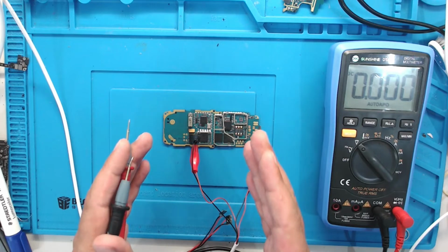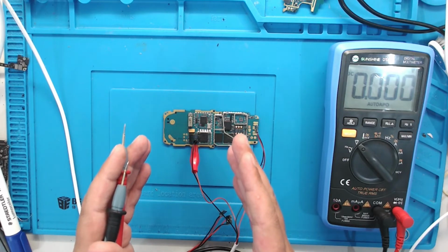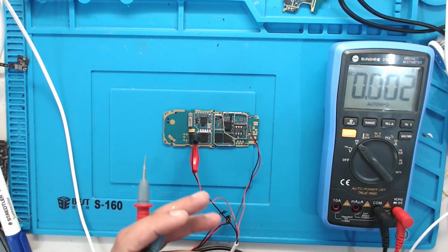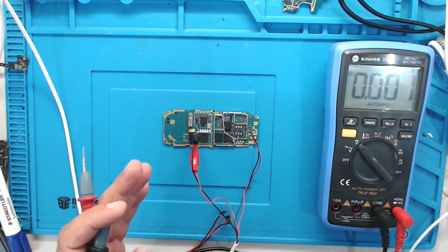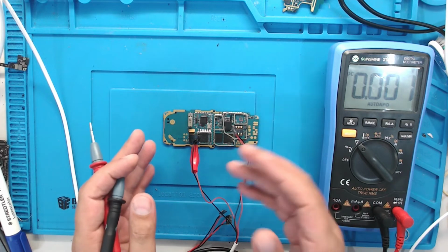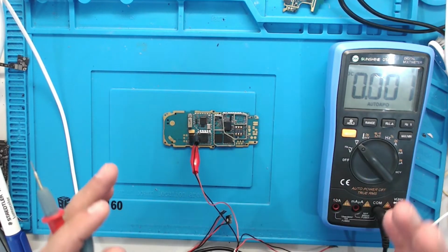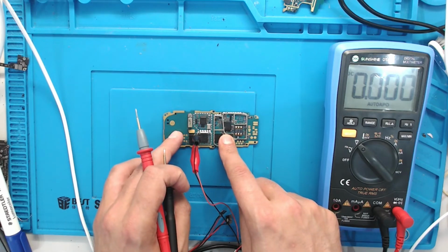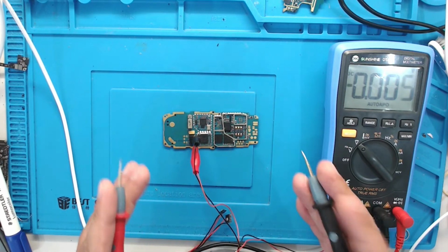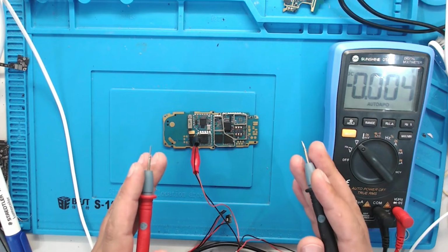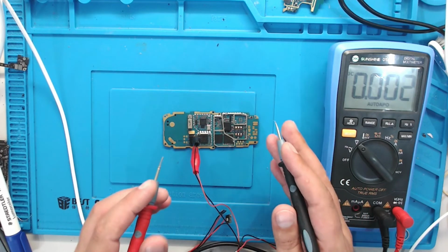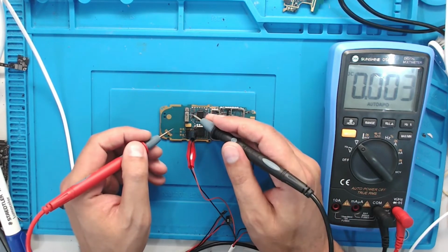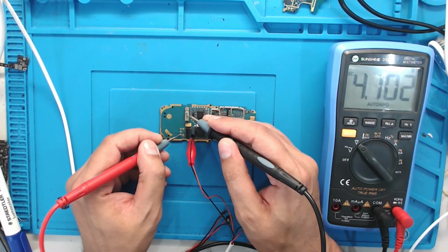Need to set the voltage around 4 to 4.2. Lower than 3.7, the phone is not turned on. More than 4.5 volts damages the mainboard. Every time, before connecting the cable to the phone motherboard, check that your voltage is between 4 and 4.2. If it's low or high, it damages the mainboard or the phone is not turned on. You see, that's the 4 volts in here.